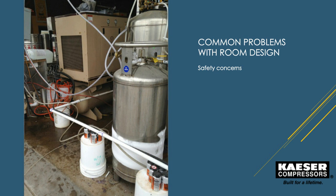Also, if your pipe is not supported, let's say this was steel pipe, the pipe should be supported. There are a lot of forces from the compressed air loading and unloading, or starting and stopping, and that movement of air through the pipe can have some significant effects, especially if it's not braced. Further, any flammables or hazards would not be recommended to be located near your compressed air system.